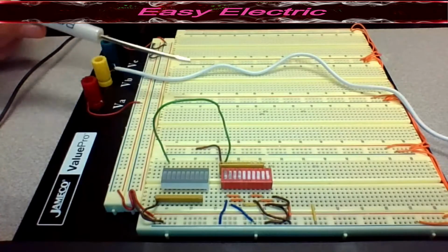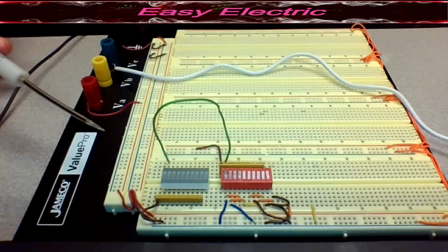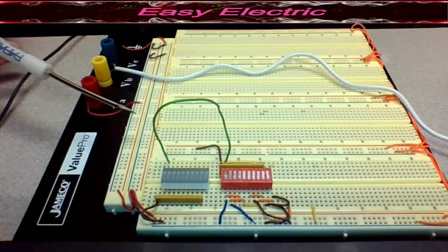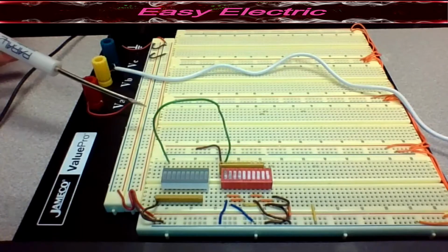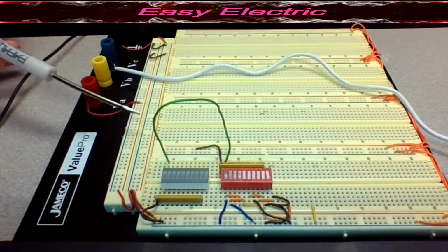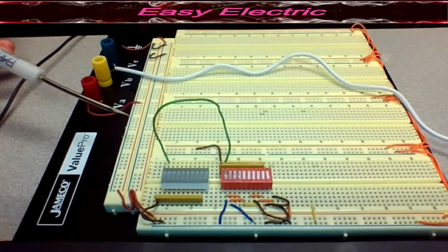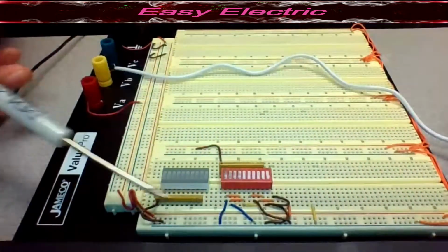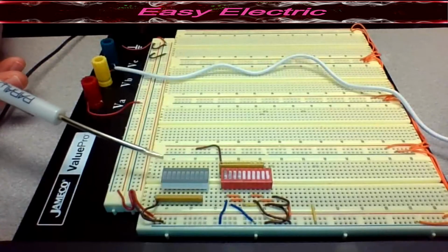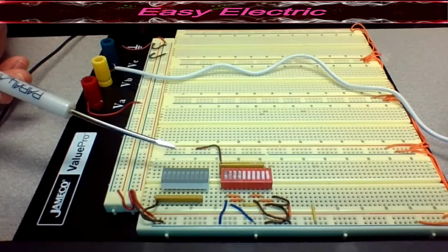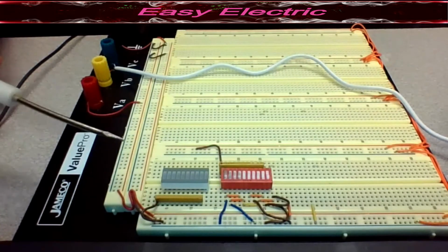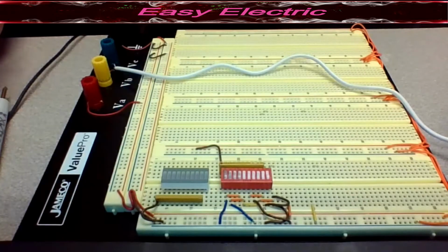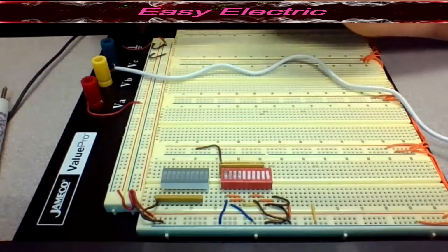Whenever you use TTL ICs, the digital 0 is 0 volt, and depending on the IC that you use in the TTL, the 1 is 5 volt. So in this project, we want to make a test bench that is able to produce 0 and 1 inputs and also check the output and see whether it is 0 or 1. In other words, whether it is 0 or 5 volt.